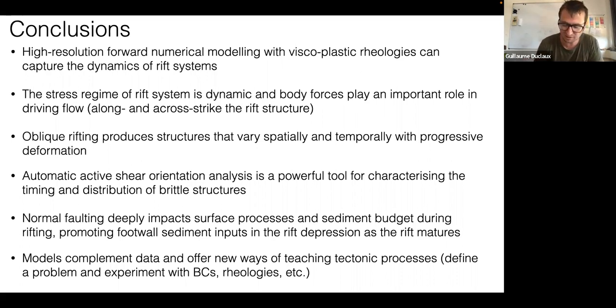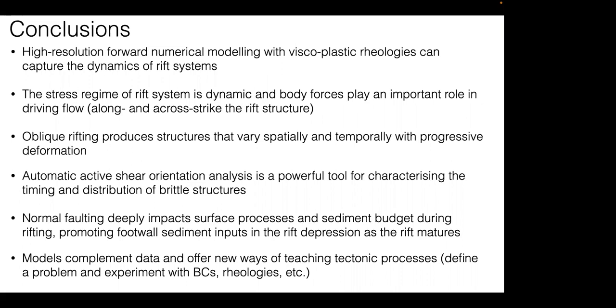The difficulty when you do this type of modeling is that it's pretty much continuum mechanics. And when you start to have a fluid come into the system, because melt is a fluid, the solvers can be a bit tricky to set, and it's two different physics mixing together. So I don't have the experience with putting melt in this type of model, but it will definitely have a massive importance. You're right.